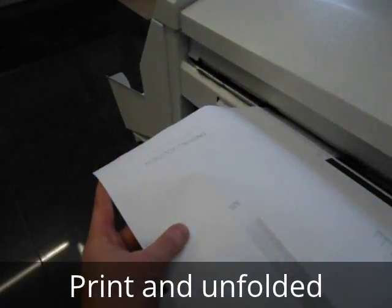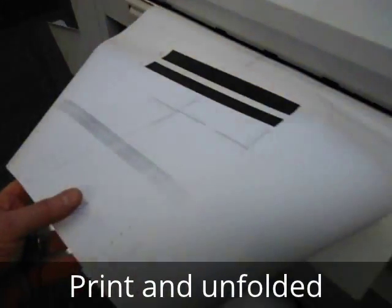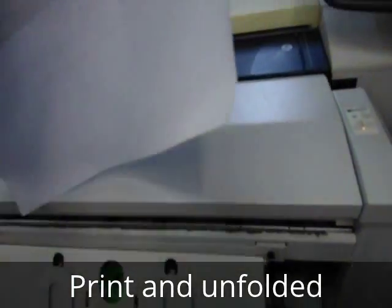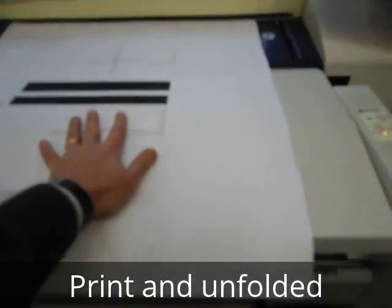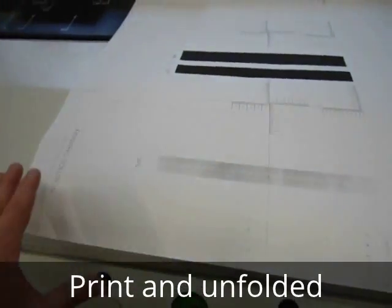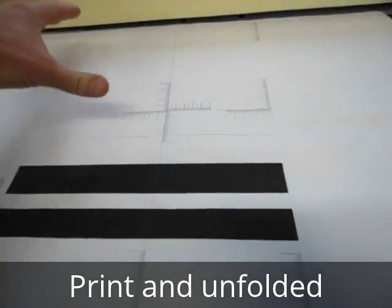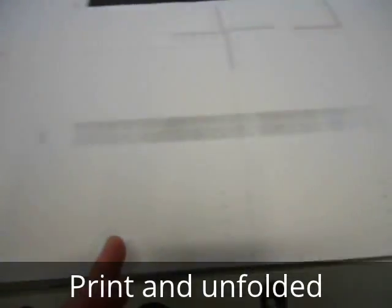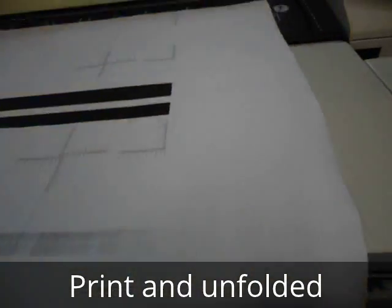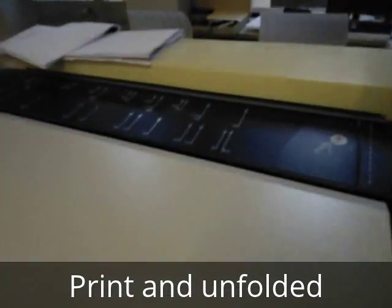So we have the title box and the blank area stays here. So now if we do the same process to have a fan fold, we will have this panel fan folded and then cross folded up to 297 plus 123, the rest is white. We can do the same fan fold.